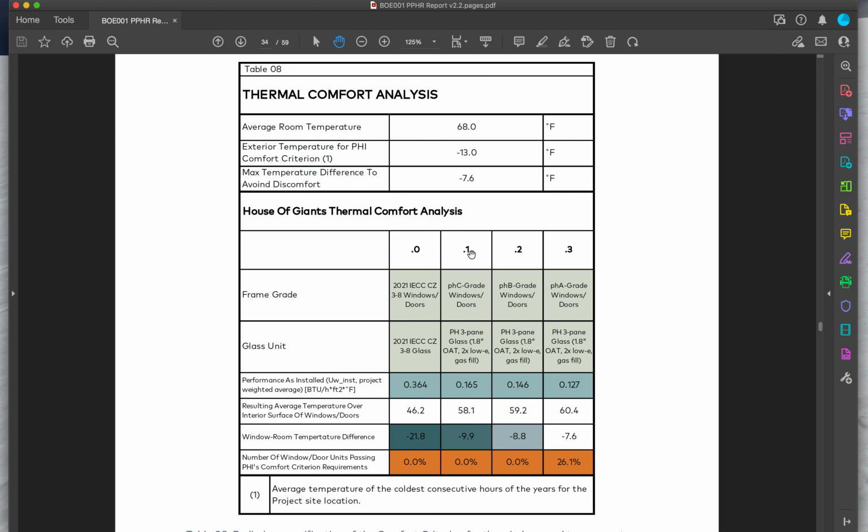Now, number 1, 2, and 3, I have switched to good triple pane. Good triple pane means a fat triple pane. That is something that it's worthwhile expanding upon. I can cover that in the next follow-up appendix video. We're talking about different types of triple pane, but a lot of American window manufacturers only have space on their frames for 1/2 inch glass, meaning that that's not enough insulation to provide extra thermal protection.